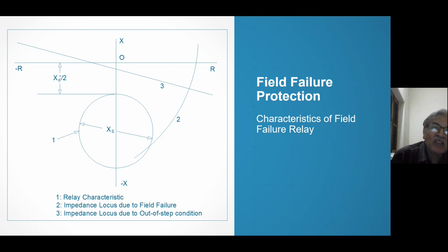But the machine is taking higher load. Therefore, its stator will start taking current ranging from 2 to 4 times, depending upon the speed at which it is finally stably working. Higher speed, but at that higher speed it will be stable because now it is sharing load. Therefore, its speed will be under control, but at higher speed. But it will take more current, so stator insulation can be damaged. The damage is due to the heat generated, I squared R T. Therefore, it's a function of time. You do not have to take action immediately, right?